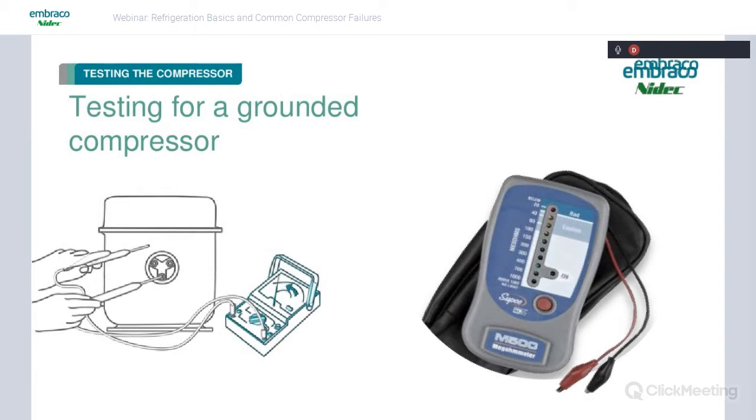The reason for this is this meter is going to put a very high electrical load on the windings, and it's going to read resistance in millions of ohms or megohms. And this is going to really test that insulation out. It's going to put a very high load on the windings and test that insulation out and read for minute leakages of current to the compressor body. And it's a very simple operation.